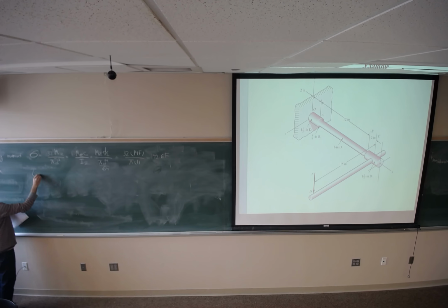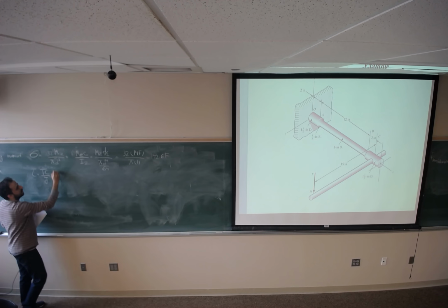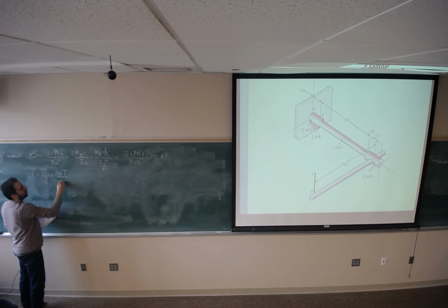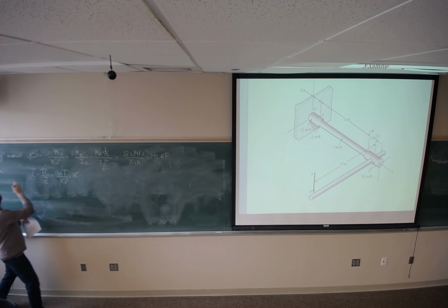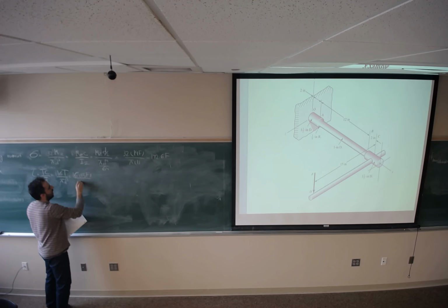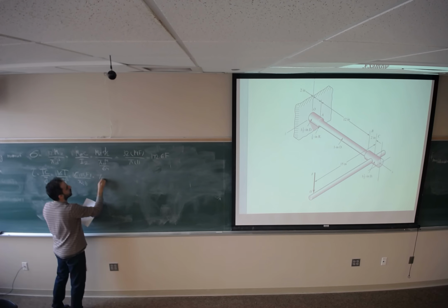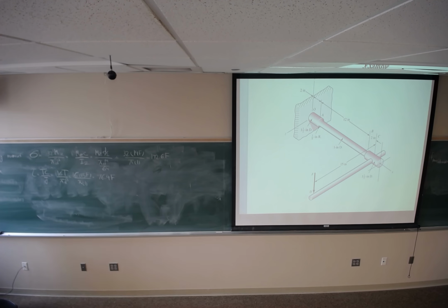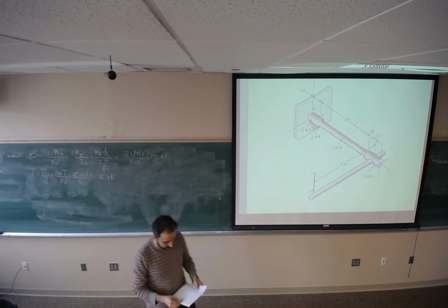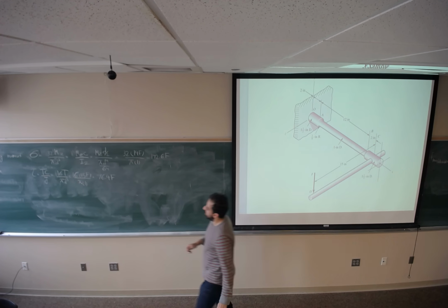Shear stress due to the torsion is going to be T C divided by J, or 16 T divided by pi d power 3. The torsion is 15F, divided by pi times 1 cubic. It's going to be 76.4 times F. These are the stresses applied to section A. This stress and this stress.